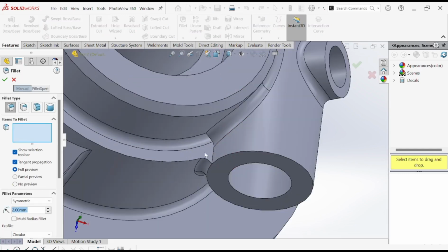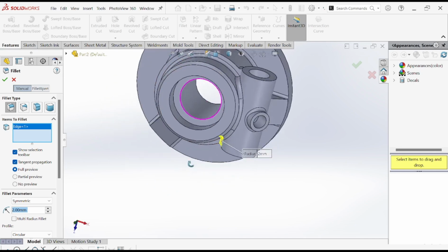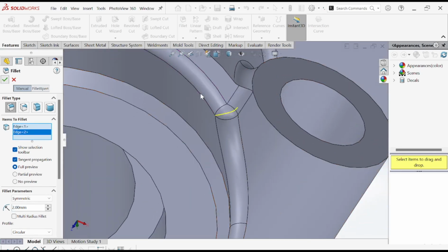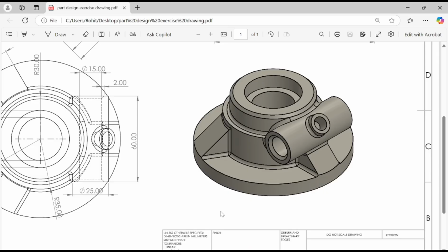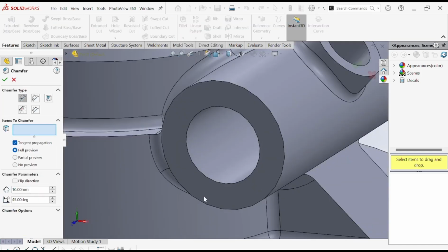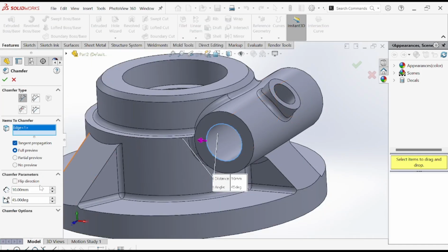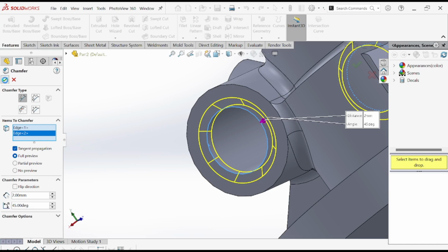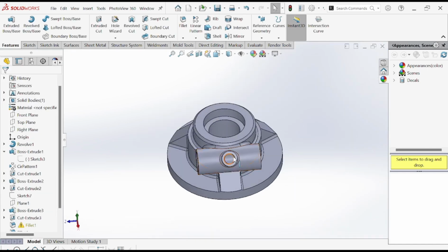Okay, just this column left. So also select this one, come here and select this one too, and make this one okay. Now here you see. Now what we need to do? What left? This chamfer. Here is a chamfer. We just need to make this chamfer, and the dimension of this chamfer is also 2 mm. So come here, select chamfer, select this one, give dimension 2. Again come here and give dimension 2 and make this one okay. Now here you see, this is our final model.